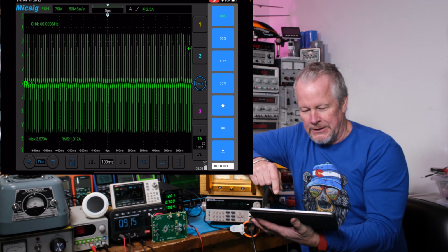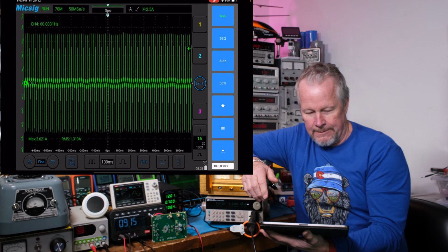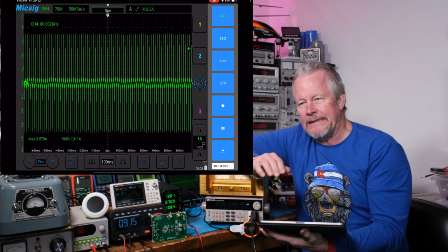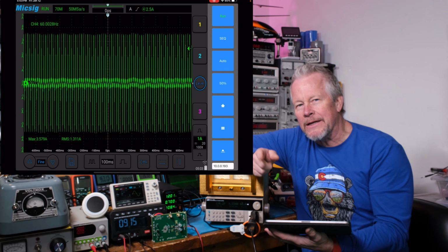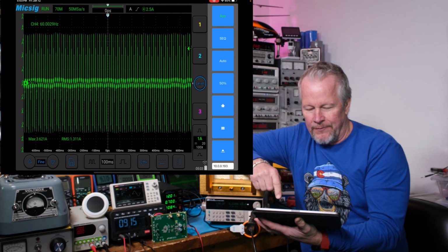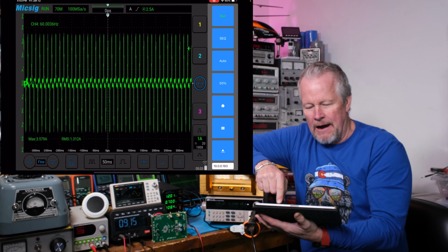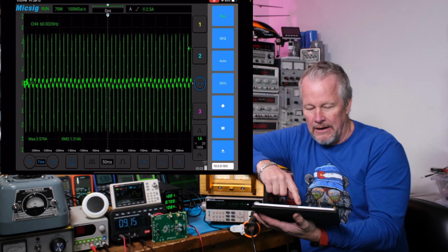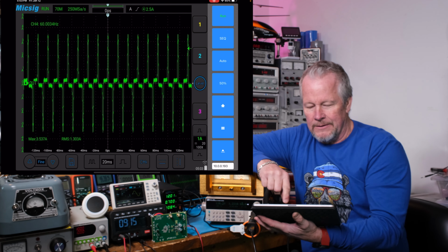So we're looking at a switching power supply, right? All those current spikes. Now, one of the things about a switching power supply is that the average or RMS current is always a lot less than the peak currents because there's an on and off period, right? And from this, let's spread it out a little bit. You can see that the off period is longer than the on period. The spikes are spikes, and the off period, yeah, there we go.